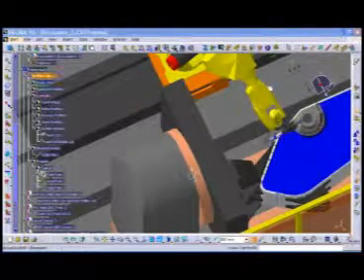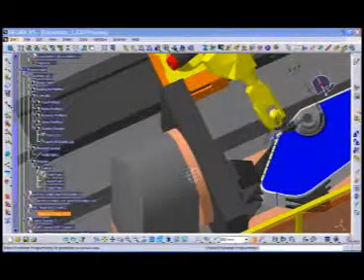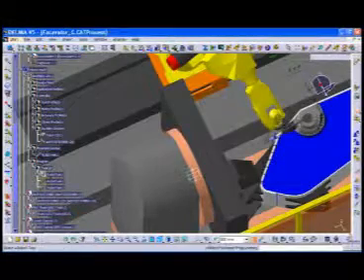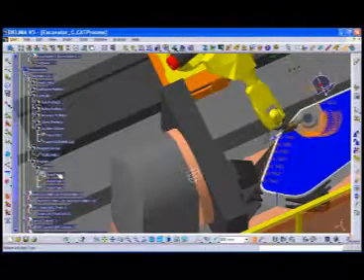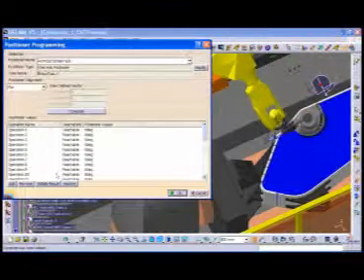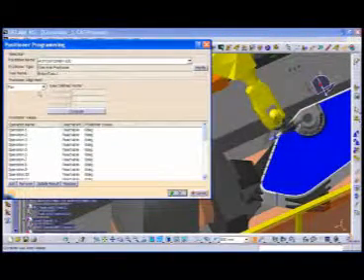The idea in arc welding is to keep the weld as flat as possible. Since molten metal flows with gravity, it's a good idea to use a part positioner to keep the weld where it belongs. Delmia gives you several options to program part positioner values.